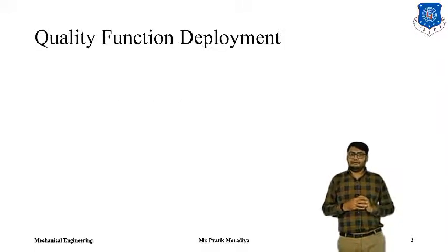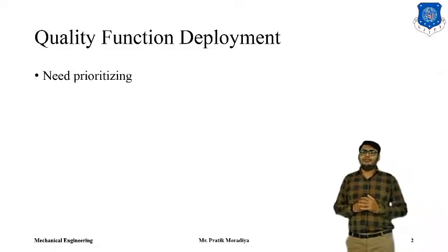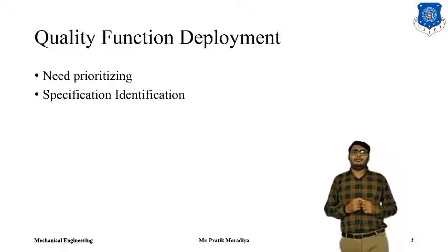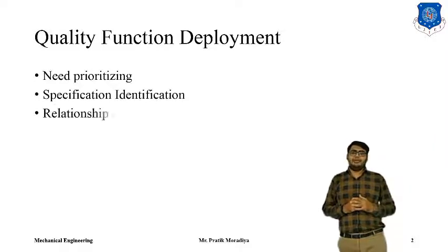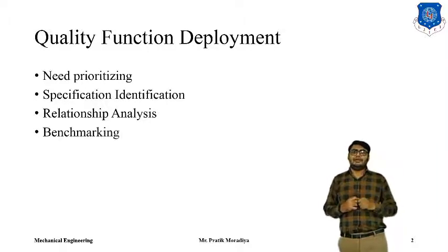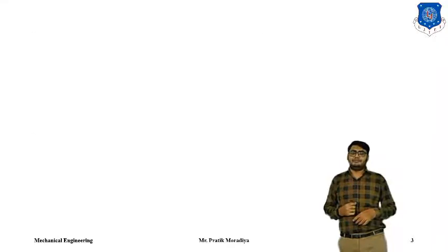Now, what is QFD? QFD, that is quality function deployment. In our case, as we have discussed, it is used for need prioritizing. It can also be used for specification identification. It can be used for relational analysis, where you have multiple properties and you need to find out relations between those properties, or you need to find out the trade-offs between those properties, where also QFD can be used. And it can also be used in benchmarking. We will see how we can use QFD in all these different areas.